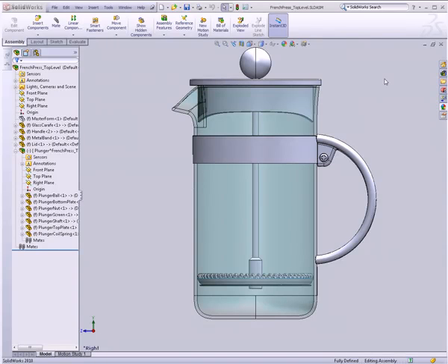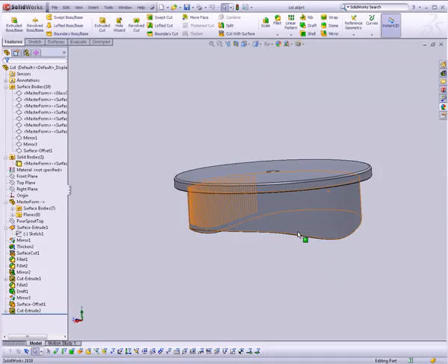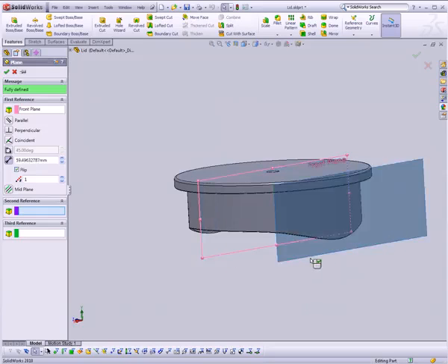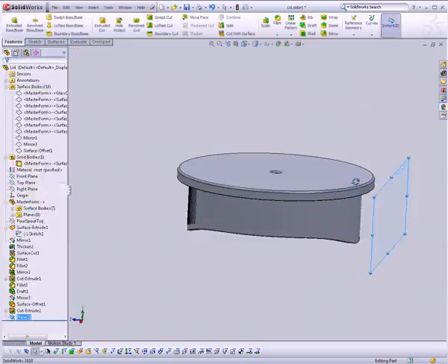So I thought I'd devote a whole video to inserting a logo on the back of this lid. Let's go ahead and click on the lid and open the part. And we want to add the lid to the back side of the surface. So I'm going to grab my front plane, hold the control key, and duplicate that plane back a goodly distance, let's just say 60 millimeters, so that it's far enough back that we don't have to worry about it.